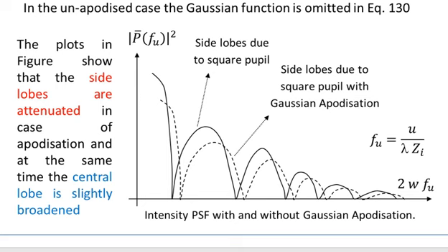And these are the side lobes. When this is the main lobe, that is the first zero. Before the first zero, we have the main lobe on the left hand side. So we have the first zero for the dotted curve and the first zero for the solid curve, and on the left hand side of these zeros, we have the corresponding main lobes.